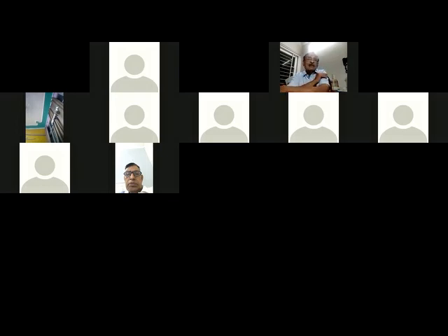Way back in '83, when at Bharat Gears I was developing gears for Maruti Suzuki, they had just forwarded the specification, and I looked at the steel grade, which was SAM420, and they had specified the oxygen content and hardenability and all that. I specified for the steel mill and the forger an aluminum content of 0.035%. Along with Indian steel mills, we sent it to Japanese steel mills.